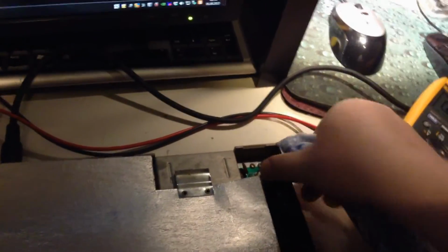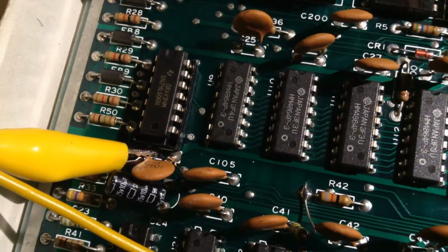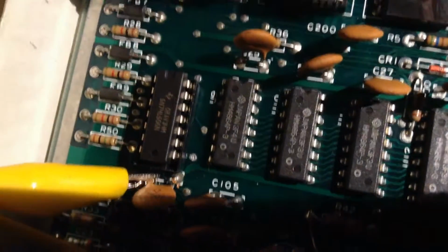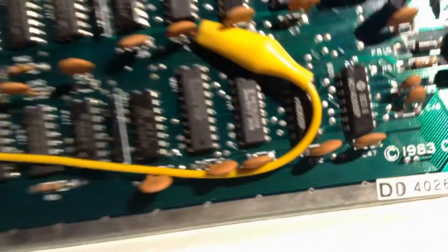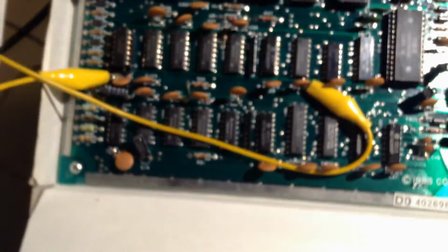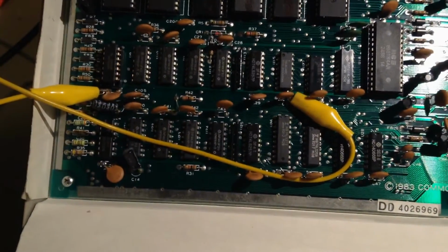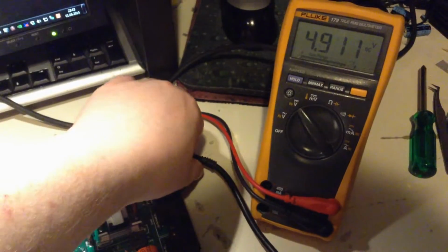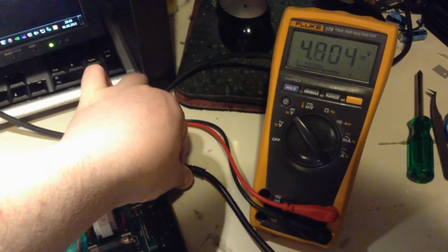Here I'm trying to recreate the fault by letting the board get hot, but the power drops when the cable is wiggled at the power plug and connector. It drops quite a lot actually, therefore I have hooked up a voltage meter near the logic IC that drives some of the serial bus lines. I've seen low voltage here before, at 4.65 volts. Can the fault be on the board?